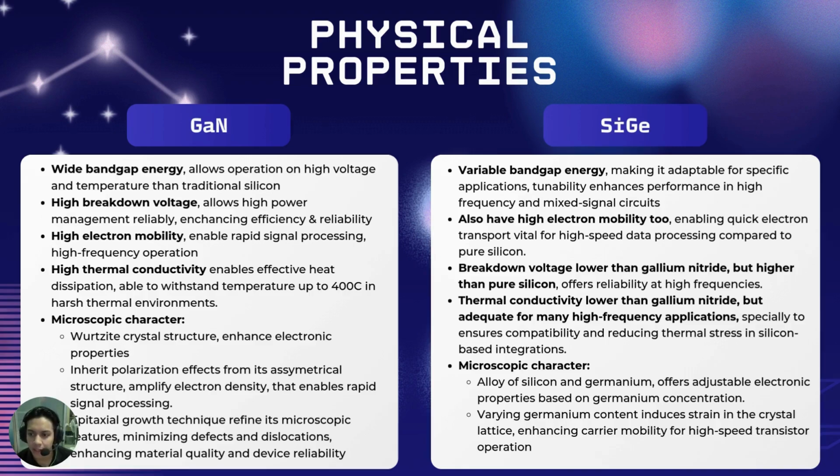While not as critical as in power amplifiers, the reliability at high frequencies remains essential. It's because its dielectric constant, which is around 11.9, affects the device capacitance and impedance, improving RF circuit performance through better impedance matching and signal integrity.